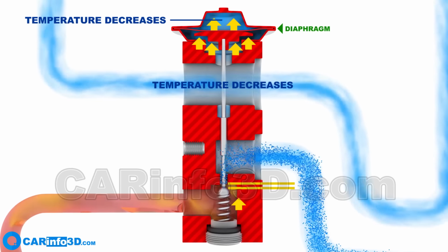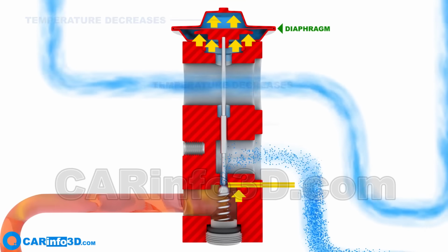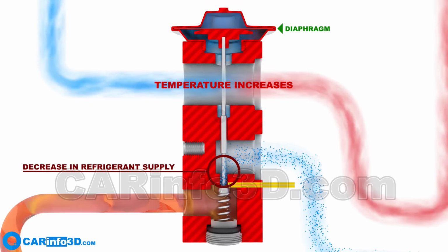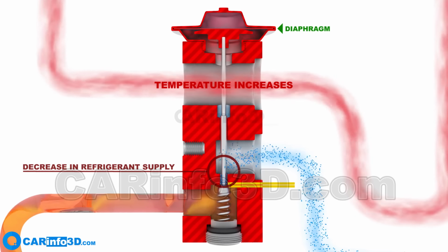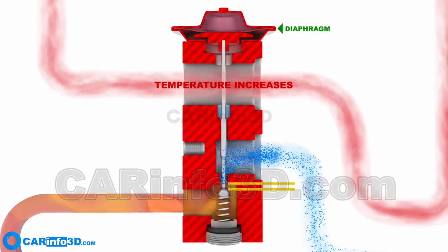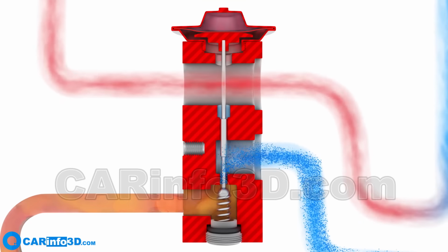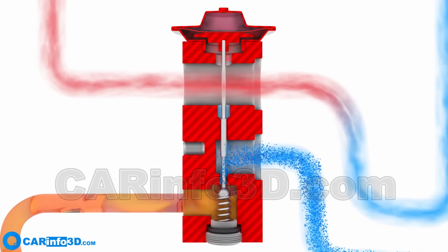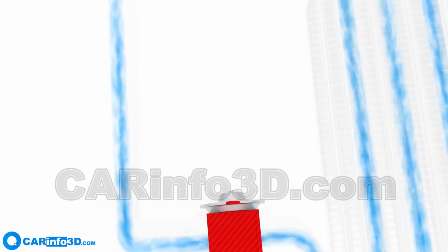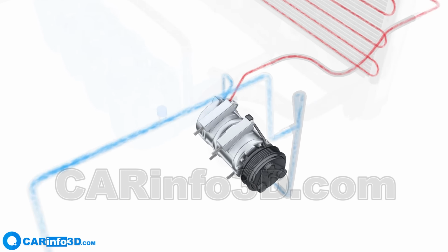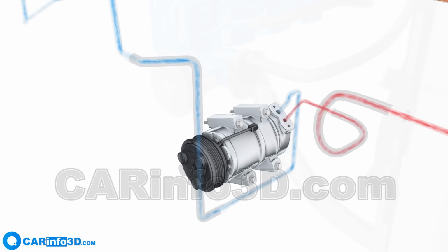As a result, the refrigerant injection rate reduces while the outflow temperature rises again. The valve, therefore, is constantly balancing to maintain a specific temperature at the evaporator output, which is determined during the expansion valve's production. The low-temperature, low-pressure gaseous refrigerant enters the compressor again, and the cycle is then repeated.